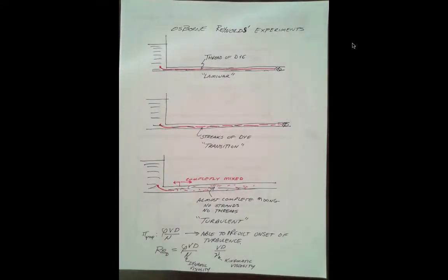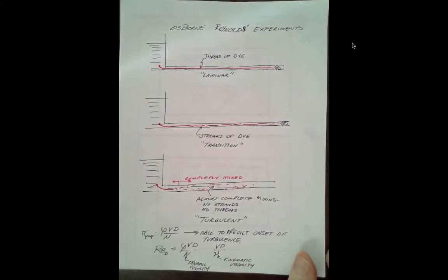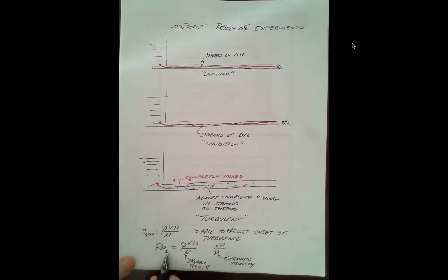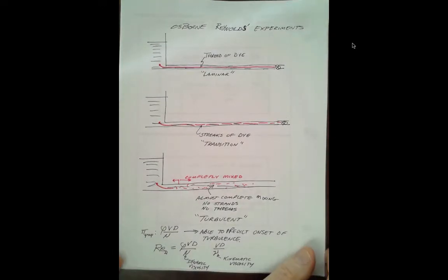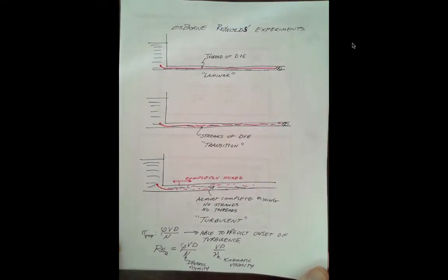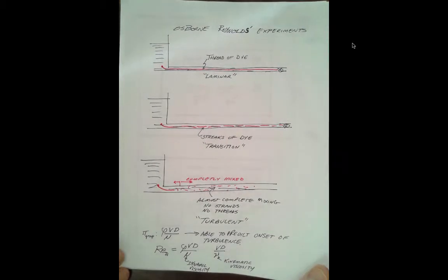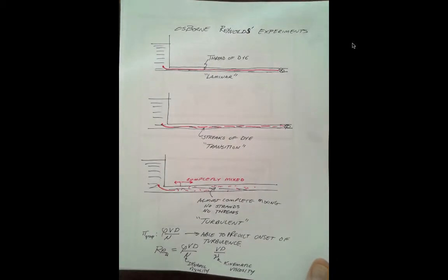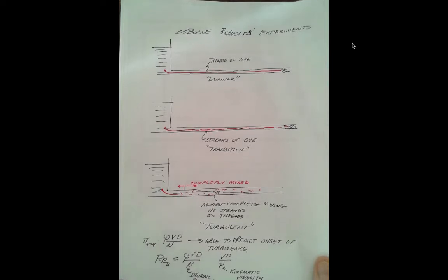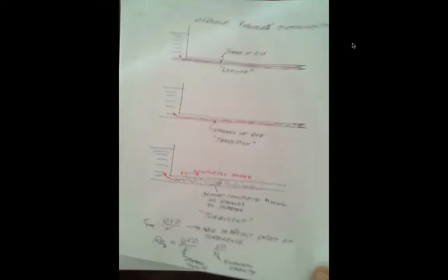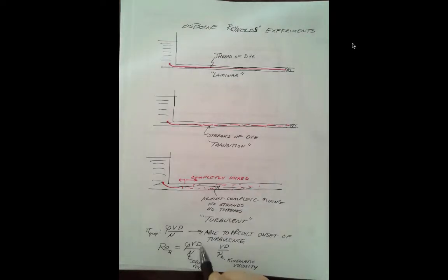All right, so there's our two ways of writing Reynolds number. This subscript changes depending on the characteristic length that's used. For example, there are Reynolds numbers based on grain sizes, and Reynolds numbers based on distance from a leading edge in a plate, and so forth. Whatever the variable is, it's going to have units of a length. It's going to be some kind of length, and so a good name as any is the characteristic length.